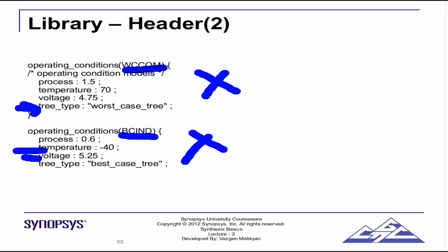Now you have to read that particular library. If I want to do synthesis, for example, I will only read the worst case library. And if I am doing a post-layout timing analysis after the design is routed, I have to make sure that my design works on all the corners defined. That is, I will perform that process 5 times, on 2 worst case corners and on 3 best case corners. The things will become very clear in Unit 5.